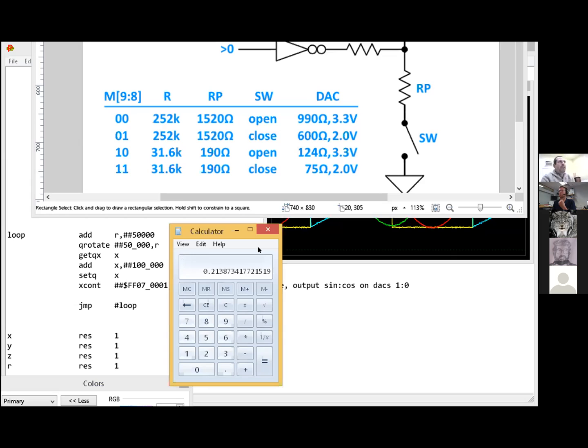Yeah, but you know the core at 1.8 volts can eat upwards of an amp if you're really running everything full blast. So this would be on the I/O pins, right? Yeah. And so it would contribute to heat. That many amps times 3.3 volts, it'd be like 0.7 watts.